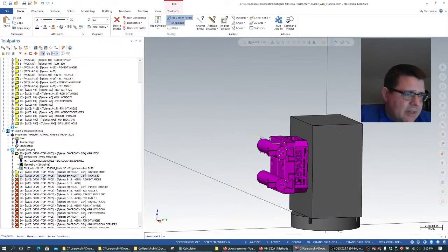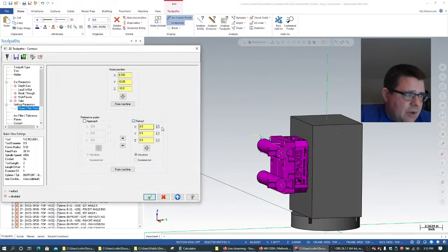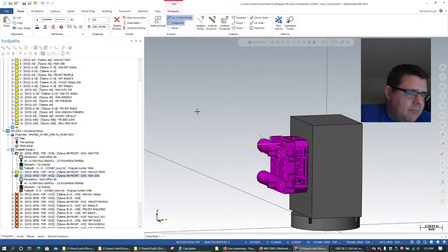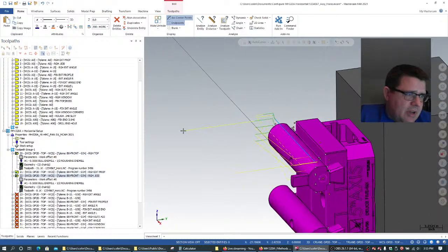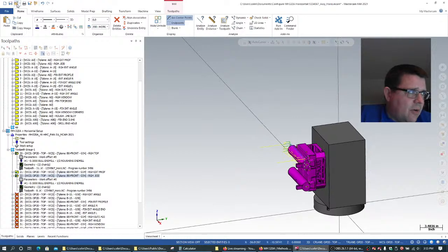Now my first path has a nice far retract. And on the very last path, because I know I'm going to rotate over here, we're going to retract to say absolute 11.5. So as I work these 3 ops, I do this high approach, I make my cutting, and then I retract out before I index.